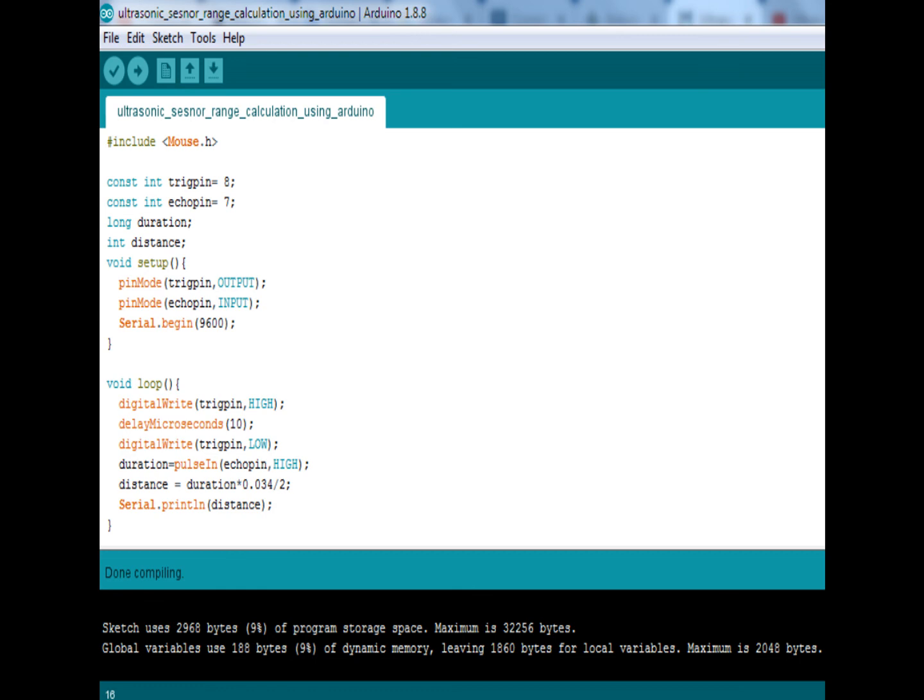For the programming code, first we need to define the trigger pin and the echo pin that are connected to the Arduino board. In this project, echo pin is attached to D2 and trig pin to D3. Then we define integer variables for distance and duration. Firstly, in the loop, we have to make sure that the trig pin is clear, so we can set that pin on a low state for just 2 microseconds. Now, in order to generate the ultrasound wave, we need to set the trig pin on a high state for 10 microseconds. We use the pulseIn function to read the travel time and input that value into the variable duration.